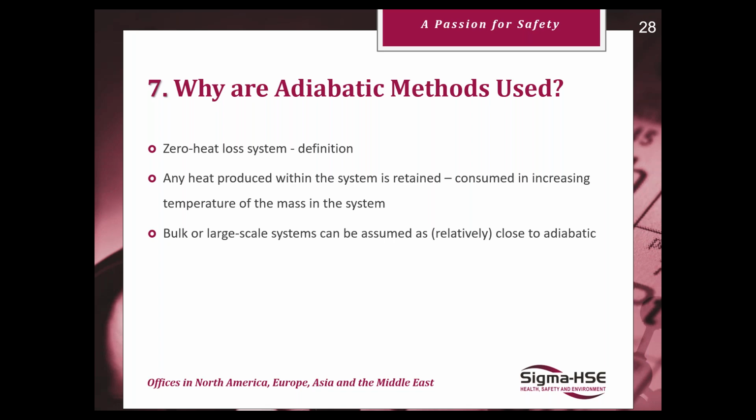These adiabatic methods allow us to measure any heat produced within the system being retained within the system, and it is consumed by increasing the temperature of the mass within the system. So that's where we talk about adiabatic temperature rises, right? Where our reaction mass goes from our temperature set point, the reaction occurs exothermally, heating up completely the reaction mass. There isn't any of that heat being generated that is being lost and spent on heating up the environment around it.